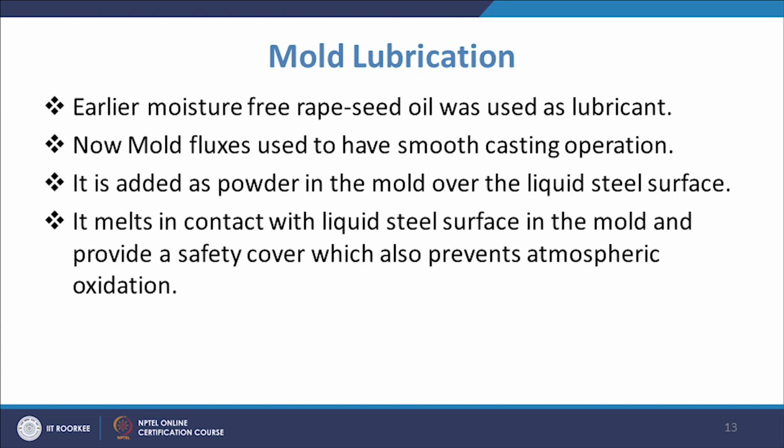Mold lubrication. Earlier, moisture free rapeseed oil was used as the mold lubrication, as we had discussed, that you have to have some lubrication so that there is no sticking. Now, mold fluxes are used to have a smooth casting operation, and it will be added as a powder in the mold over the liquid steel surface. So, that is the normal practice.